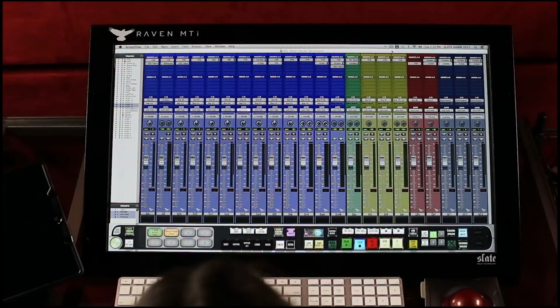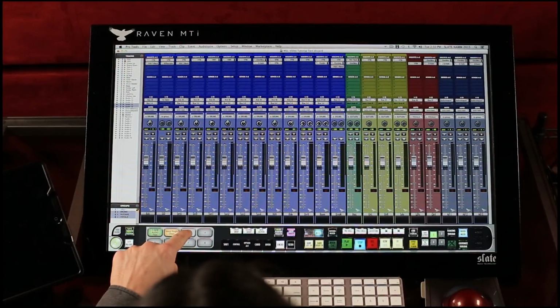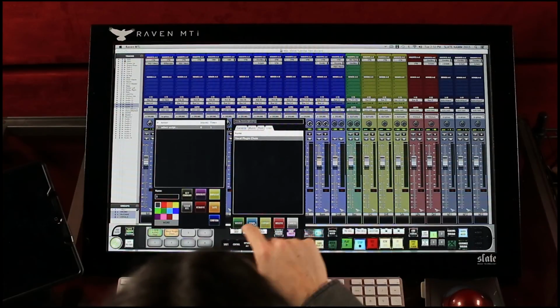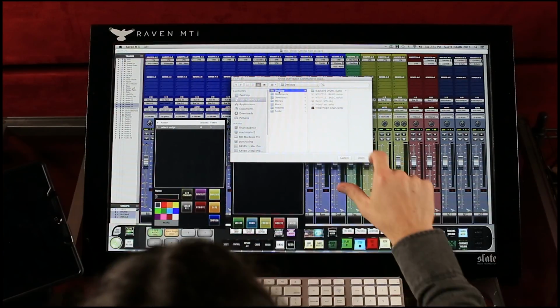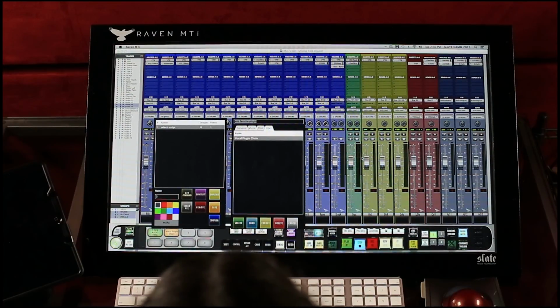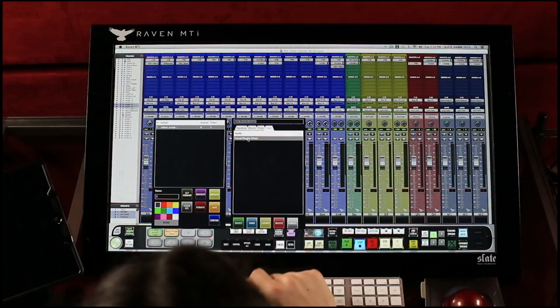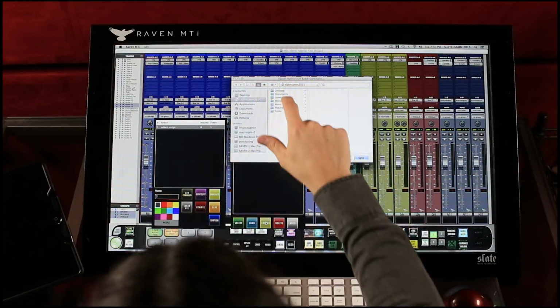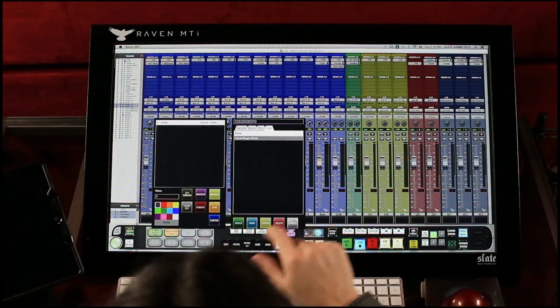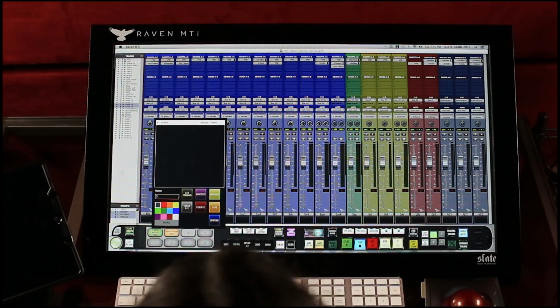Importing a batch command is simple. In the Batch Command System menu, hit Quicklist and select the User tab from the top. Now hit the Load button and locate the .ravbc file on your computer. Select the file and Raven will import the file into your User tab. Exporting is similar. From your User tab, select one of your saved batch commands and hit Export. This will save the file to your desired location and can now be shared with other Raven users.